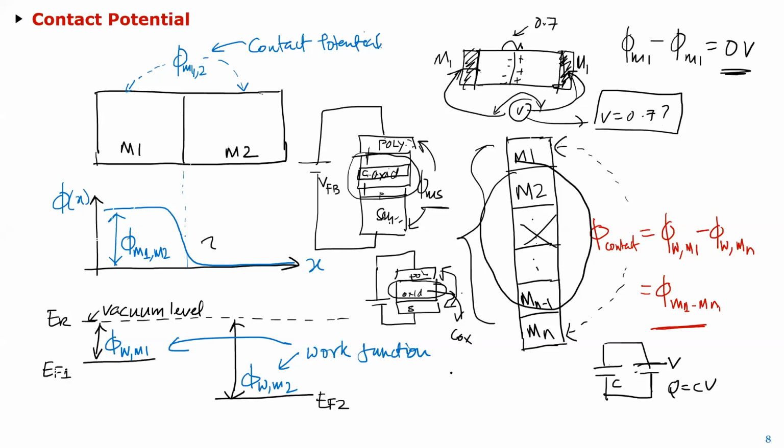And what this is saying is that, by the way, first you have to make your V equal to phi ms. So let's say that was 0.5 volt. First you have to apply 0.5 volt. After that, you'll see the oxide capacitance, which is Cox times the area times V minus 0.5, just like the threshold voltage. I think that's what it is saying.